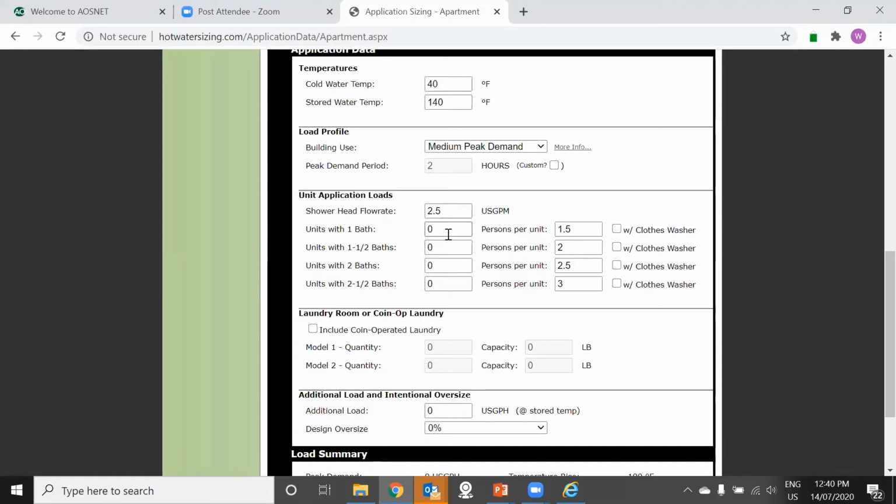Going back to the tankless there and answering this question on the recirculation system, we have a tankless model that has a built-in recirculation pump in it. It's ideal because you can program it to be on a timer. So 2 time periods per day, you can have it set so that from 7 a.m. to 9 a.m. it is circulating, and then shuts off and turns back on again at say 5 until 9 or so.